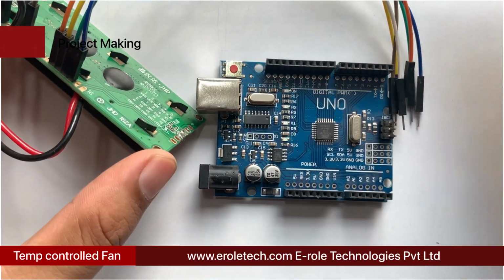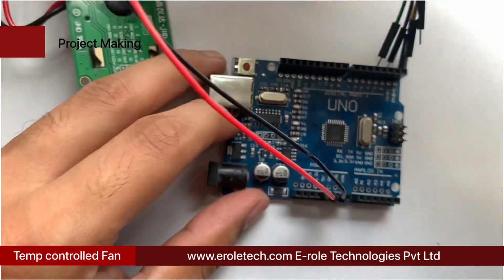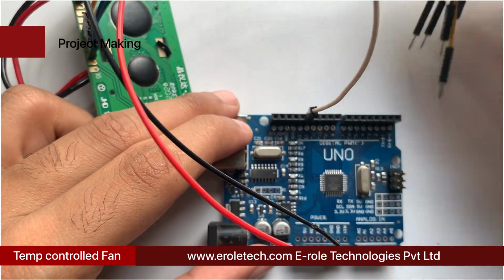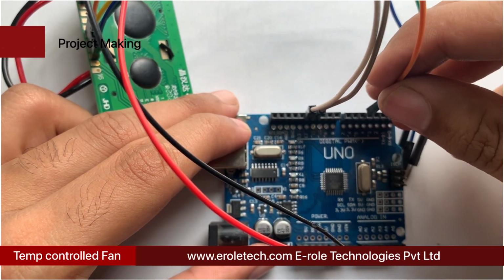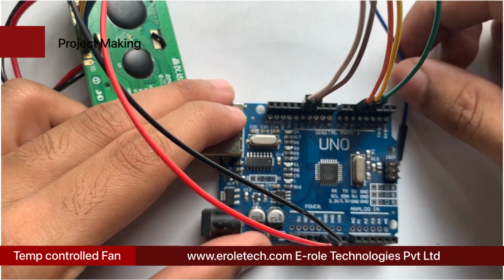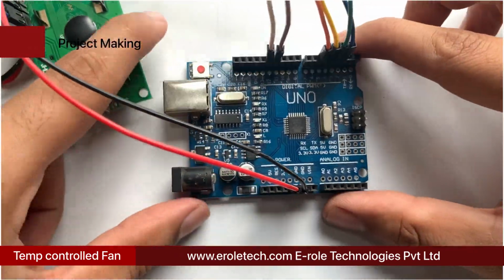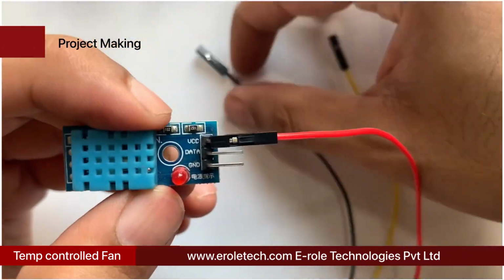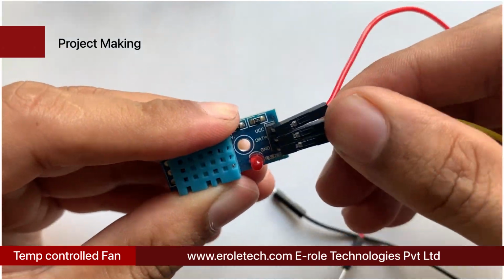Now we will connect the LCD display with our Arduino hardware board. Connect the red wire with the 5 volt pin and the black wire with the ground pin. Now connect the white, brown, orange, yellow, green, and blue wires with pin numbers 12, 11, 5, 4, 3, and 2 of Arduino respectively. Connect a red wire at the VCC pin, a black wire at the ground pin, and a yellow wire at the output pin of the sensor.